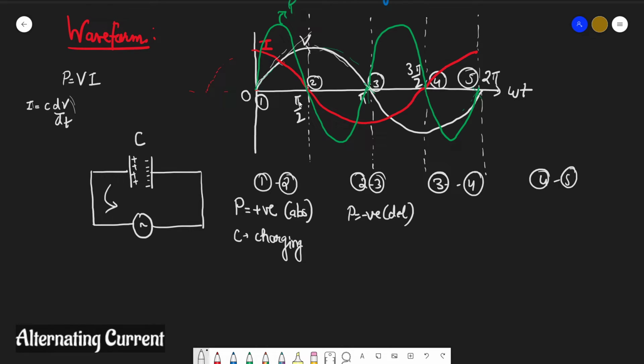And you can see that the slope of voltage is now on the decreasing side. That means current reverse and the slope is decreasing. The charge accumulated in the previous cycle will be getting depleted in this capacitor. So I will say the capacitor is discharging now. While discharging, these charges are depleting from this capacitor, and the capacitor is delivering power to the source.